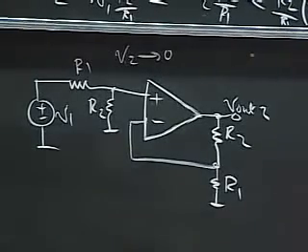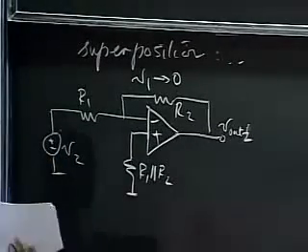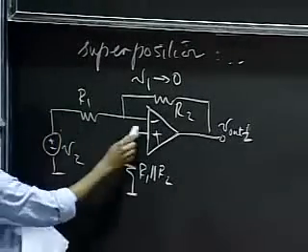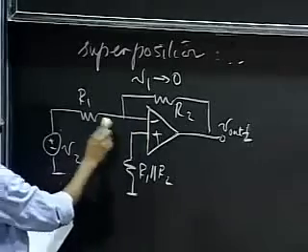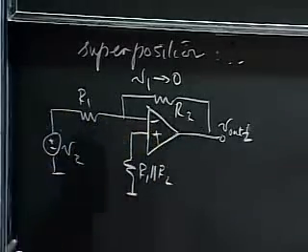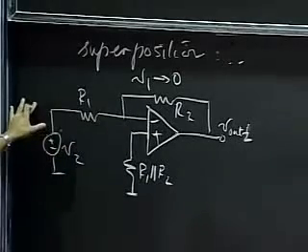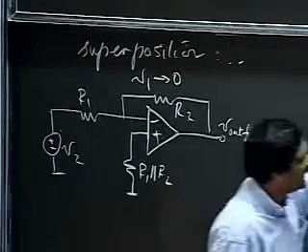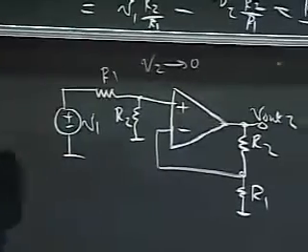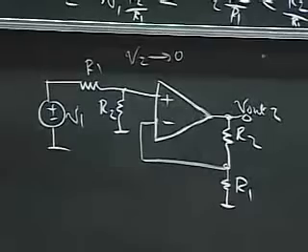Let me go ahead and solve this circuit. It turns out that this is also a pattern. I'll analyze it today, but in the future, V2 going to this node through R1 and then R2 to the output, you've probably also seen this in your recitation. This one is called an inverting connection, and this one here is called a non-inverting connection. So let's go ahead and do V out 2.